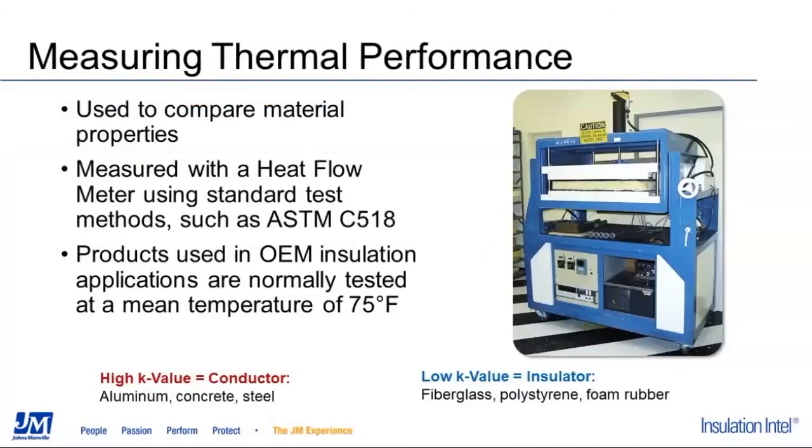So how do we measure thermal performance? Thermal performance is generally measured via a steady state heat flow meter. We use ASTM C518, which dictates the method for that. In OEM insulation, we would typically test products to a 75-degree mean temperature.